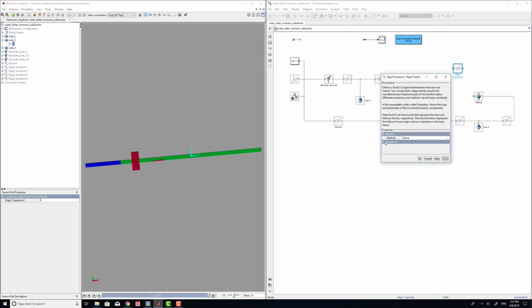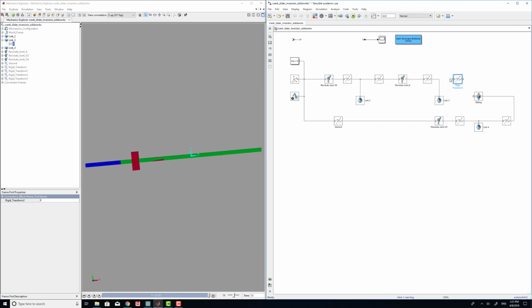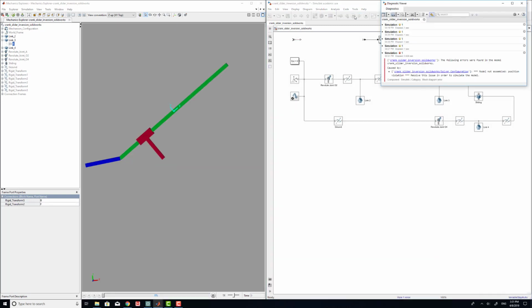So as I mentioned before, we can use rotation to change axis. You select align axis because we don't want x motion, we want z motion. So your x becomes z and z becomes x. And in such a way, we can connect your link number 3 and the prismatic joint. You can check it out.